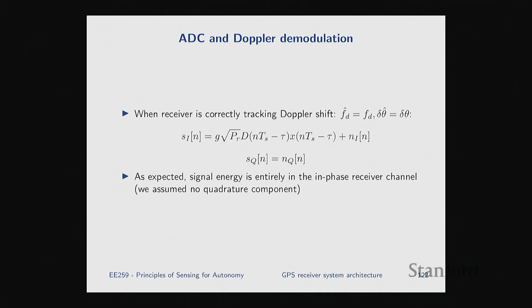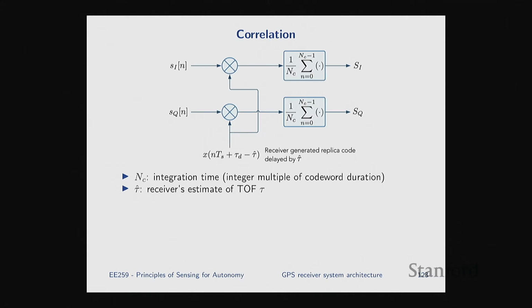Why? Because here what we don't like is, well, this is just a constant, G times root P. That's fine. Multiplicative constant, don't care. Noise is always there. You're never going to get completely rid of noise, so fine. It's going to be some noise added to the output of the correlator. It's the LNAV message here that's annoying, right? But is it really annoying? And the answer is no.